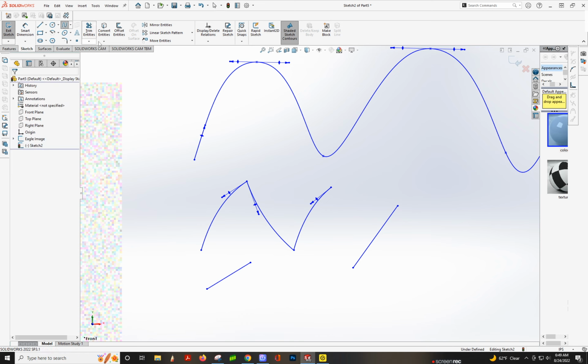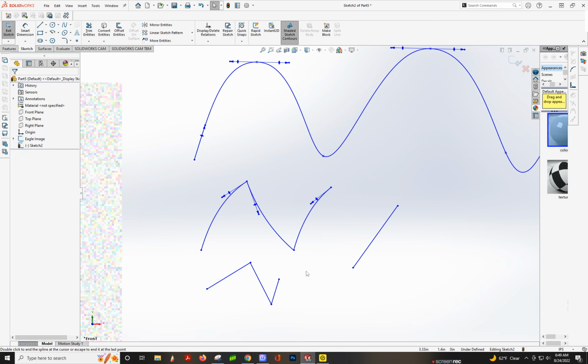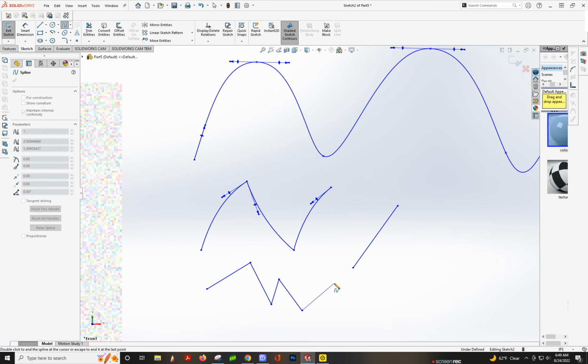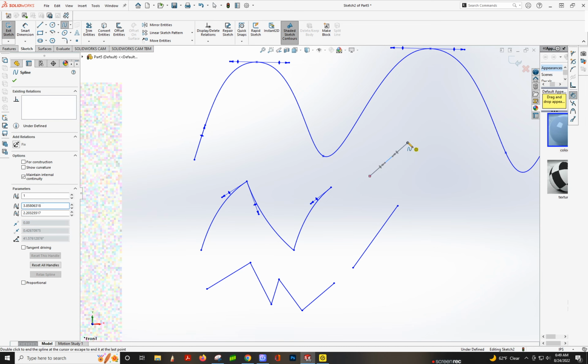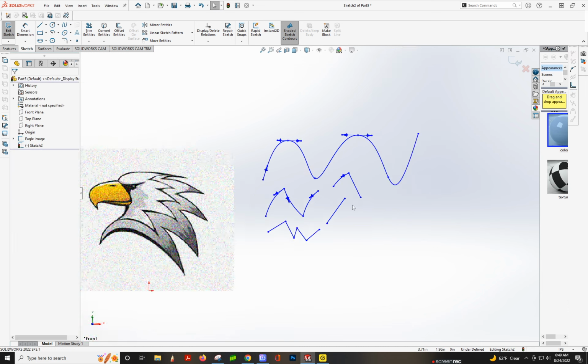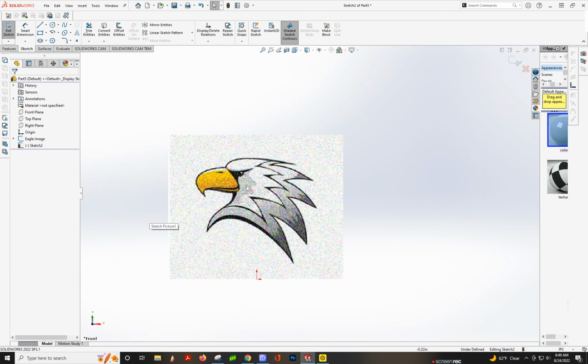So other tutorials, I'm going to be doing that. And then you click on the spline tool, click, click, escape. You get fast at it. Escape, and then I have a hotkey thing. So I right click, drag, and then I can do spline. But yeah, it's easier to do the double click. And then just go in and adjust handles. Okay, hope that helps. Everybody screw around with that a little bit before you start doing this.